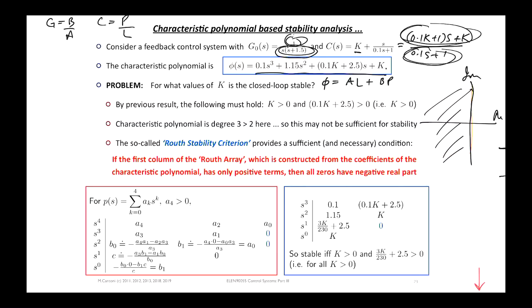But lambda(s) is, in this case, G(s) times C(s), which is K times 100 on s times 0.01 s plus 1. In the limit as s goes to 0, that goes to infinity, and then you get 1 divided by 1 plus infinity, which is 0. Right. Okay, make sense?